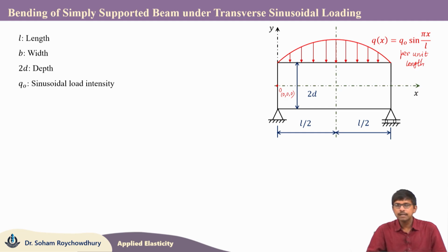Now, once the beam is subjected to this sinusoidal load intensity, for finding the reaction forces at both the left hinge and right hinge, the 2 simple support points, 2 hinge or pinned joints, we will be having the vertical reaction forces, which will be obtained by using the symmetry of the problem, and also by using the vertical force balance.